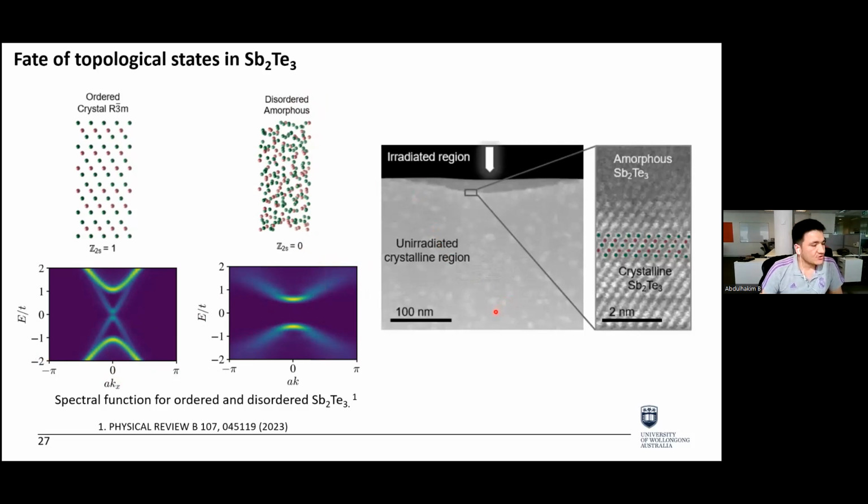Now, as I showed very early, I did a lot of work using focused ion beam, TEM and STEM to study the atomic structure of this crystalline material, to really not introduce disorder during sample preparation, but rather to reveal the real atomic structure. As you can see, when it's irradiated with different ion beam energy and different ion beam fluence, we could introduce disorder or amorphization, where you can clearly see this transition between amorphous and crystalline structure.